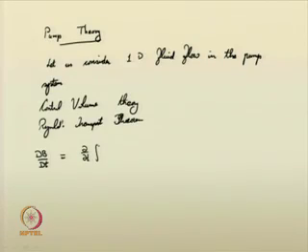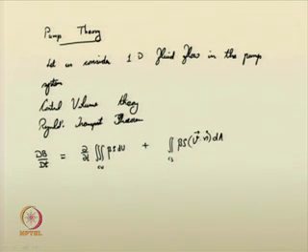So, the material derivative of that quantity is nothing but the net amount of that extensive property generated within the system plus the integral of rho B V dot n dA. So, this quantity is the net outflow of that extensive property through the control surfaces of the control volume, right.